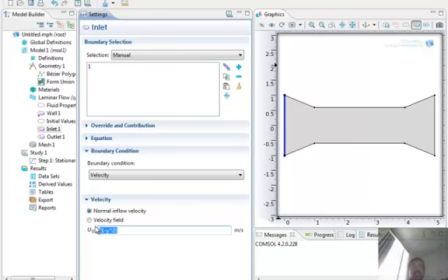This one will have a 0 velocity at the boundary because y equal to -1 gives 0, y equal to +1 gives 0. But y equal to 0 in the middle of the channel, it will be 1 meter per second, the maximum velocity. That's what you're asking, right?